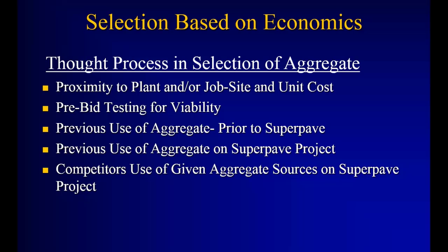And so if you're starting a project end of May, and it's an 80,000 ton asphalt mix, FAA 45, say, for example, that's what, 76,000 tons of aggregate plus any stockpile loss and plant loss. So you've got to haul roughly 80 or 90, haul and produce 90,000 tons of aggregate and get it in place for when the plant comes in May and gets set up and calibrated. So all that comes into play.